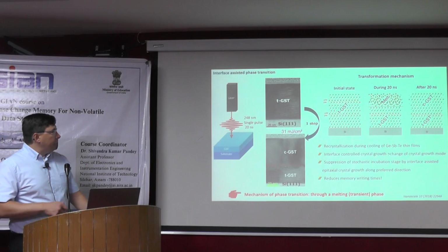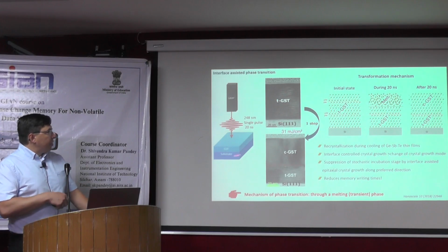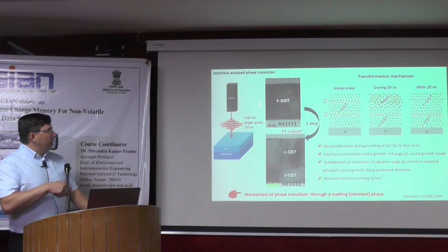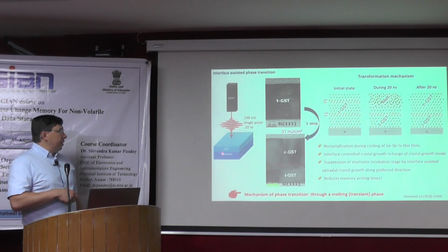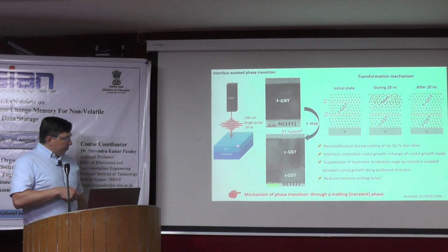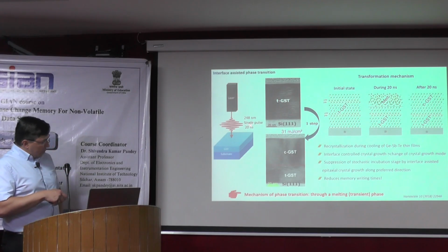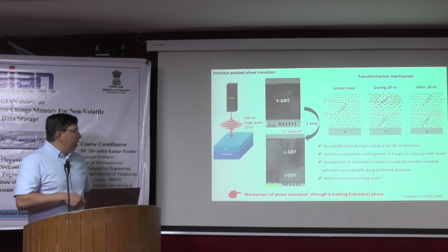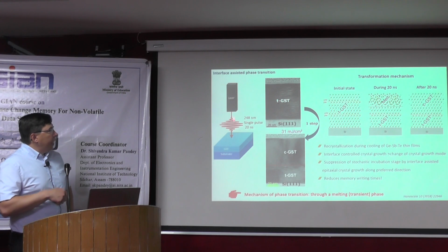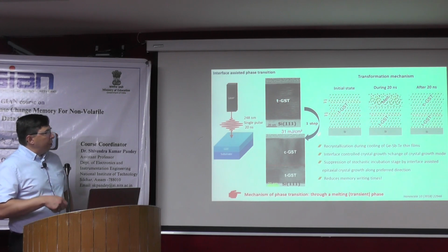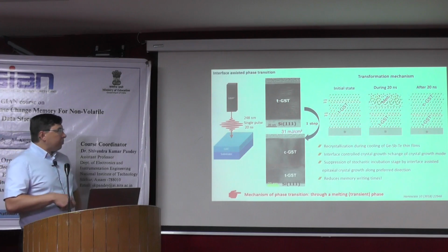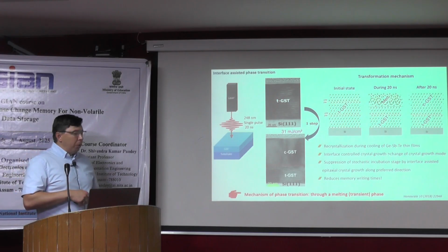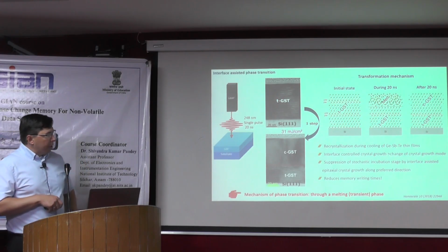In this case, if you have the TGST, the stable trigonal phase, as an epitaxial thin film, and we irradiate this system with a UV laser, 20 nanoseconds pulse duration, wavelength 248 nm, an excimer laser, then we can transform our TGST to the cubic GST. But in this case the transition does not occur through solid-solid transformation, so it's not a crystalline to crystalline transformation.